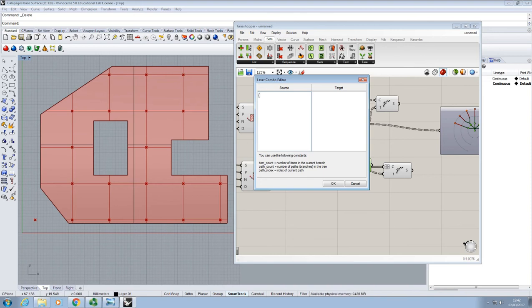To give you an example, we'll put in a curly bracket, because we're defining this as a set of branches. Then we'll type in A, semicolon, B, semicolon, C, semicolon, D, and then close off the curly brackets. What this is doing is labeling each one of those levels of branching in our input list. Using those same labels, we can now map that into the form that we want. In this case, to match that data structure going into C, we want curly bracket, then a 0, then a semicolon, and then D.